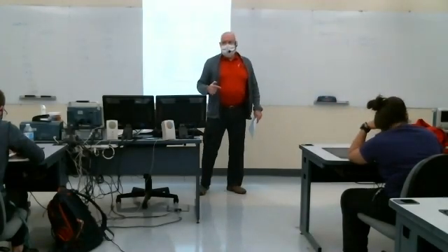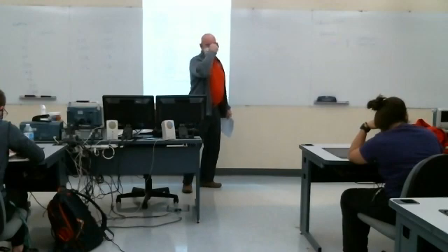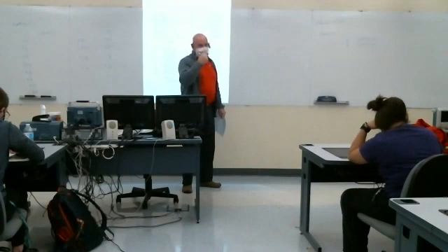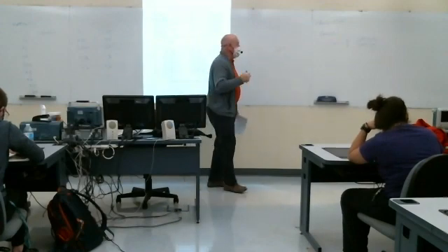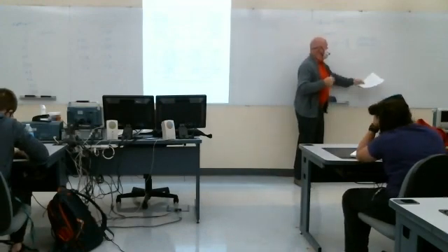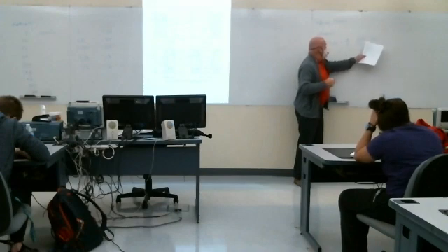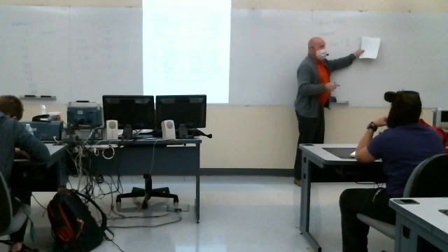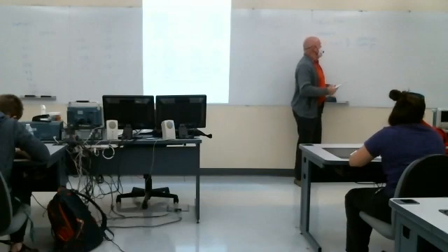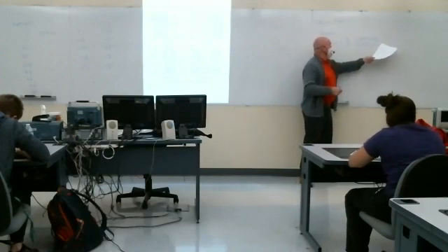This would be a first order filter. Certainly by looking at it, we can't really tell whether it's a low pass or a high pass filter. Actually, you probably can. At low frequencies with omega equal to 0, this is going to be like 1.6 over 10. It looks like it has a gain of 1 at low frequencies, right? With omega equal to 0. As omega becomes really large, the j omega terms are going to dominate these constant terms, and this is going to approach 2.